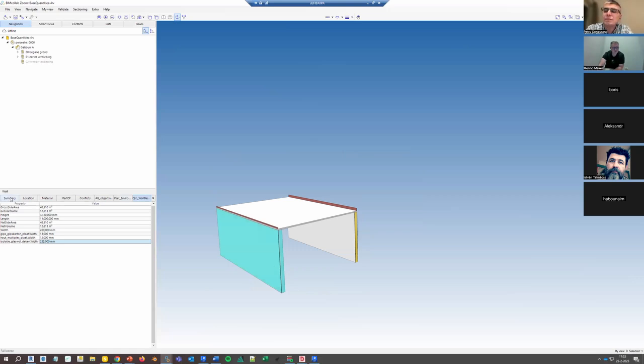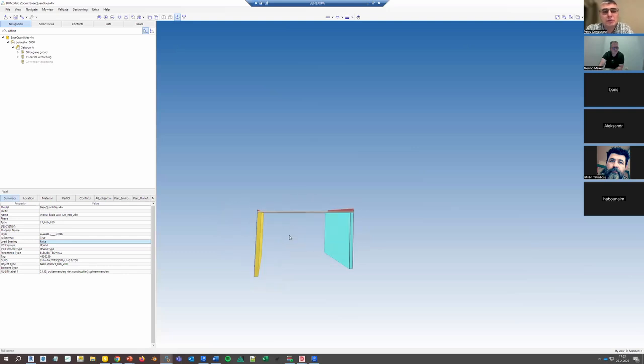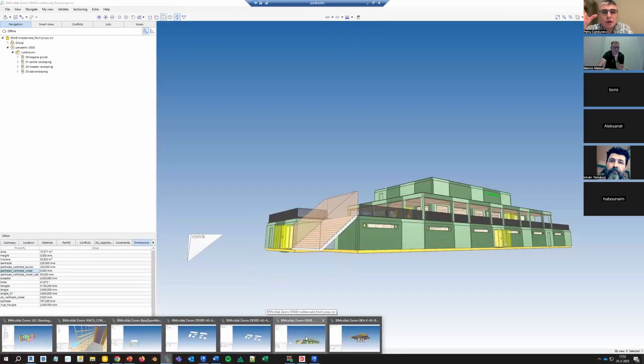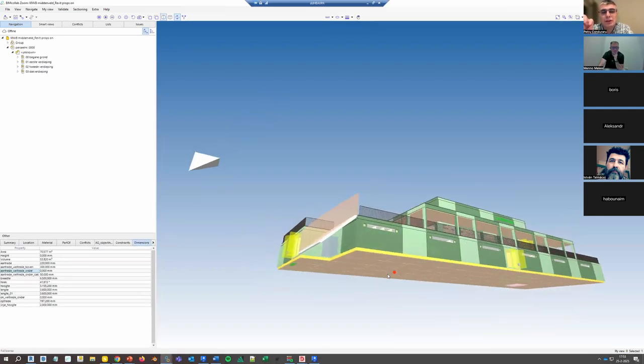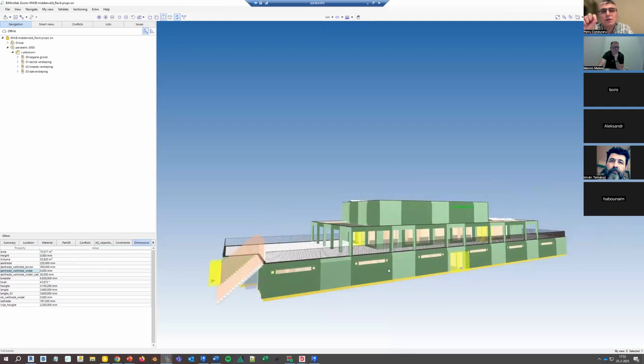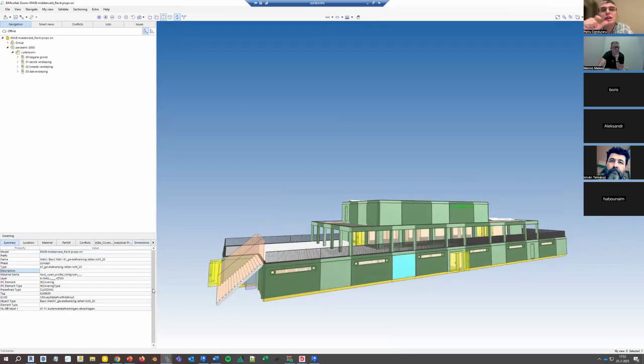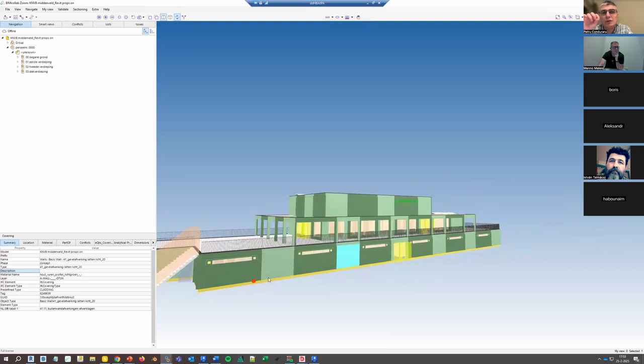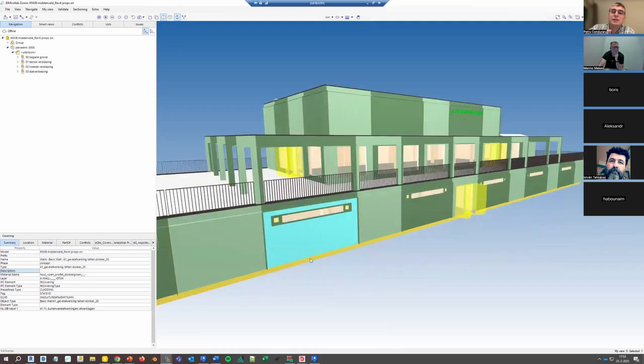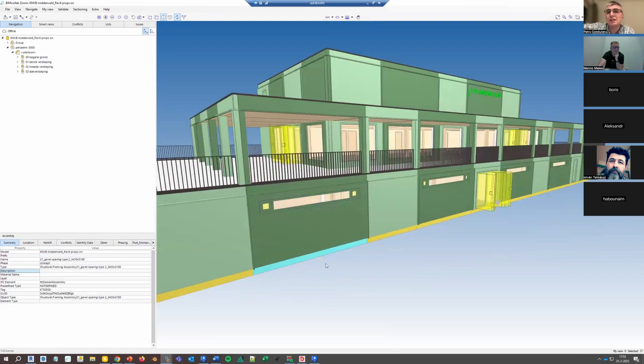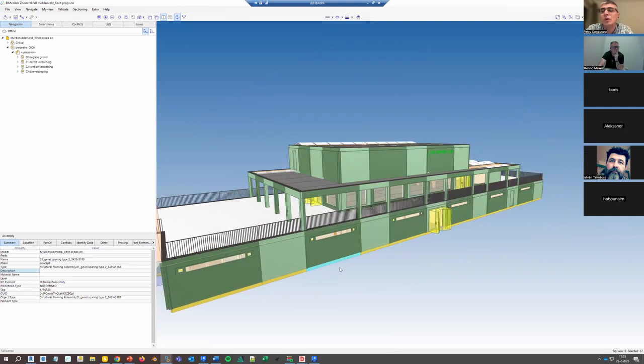I'm not sure what you mean with duplicate types. So when you export a model to IFC, like if you know what an IFC wall type is, for example, Revit exports each type for each occurrence. But in IFC, you can have just a type and then that occurrence instantiated in all the places where you have the wall. In Bonsai, you can see many types which are actually about the same wall.